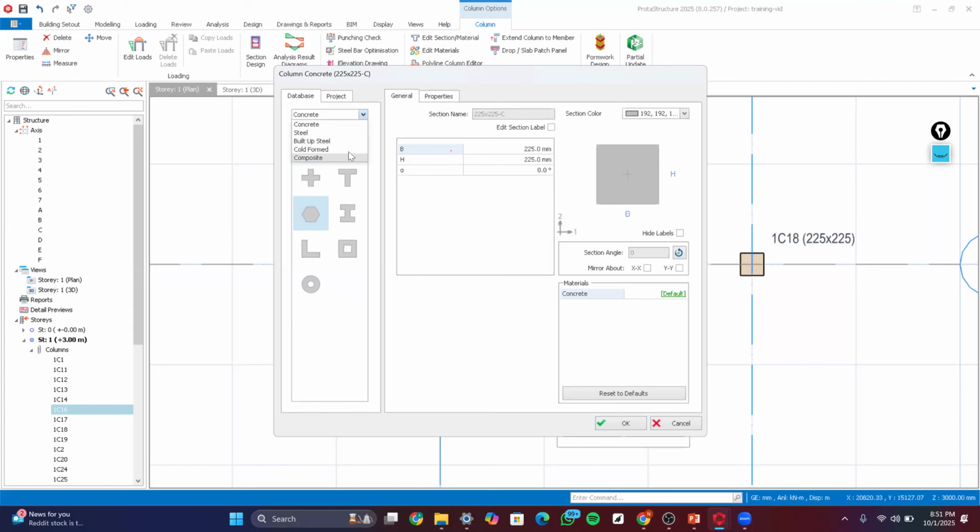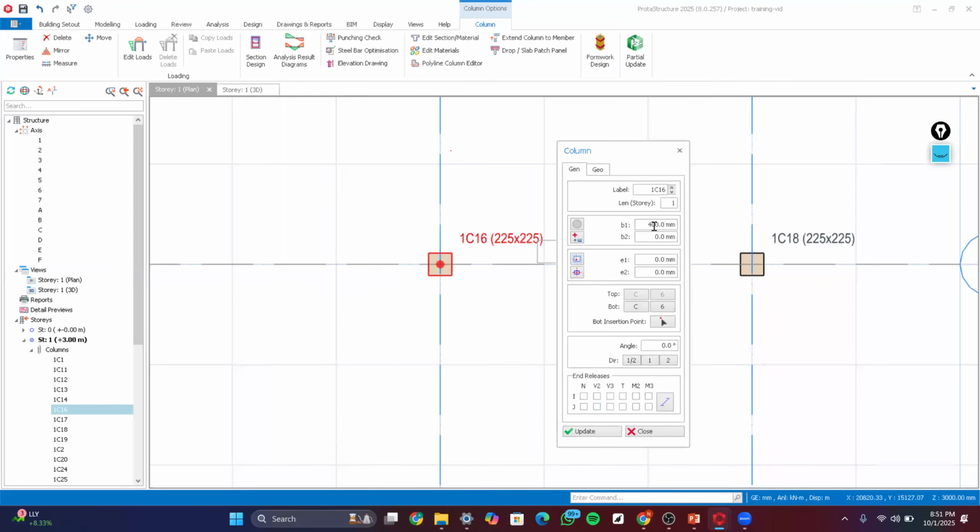Okay. So in this case, I'm going to select the circular section if I want to change that to circular. We have the option to also change the diameter of that. Let's leave this as default. We will still have the option to change the diameter in the properties dialog. So when I've done that, simply say OK. Then we can now modify the diameter of that circular column.